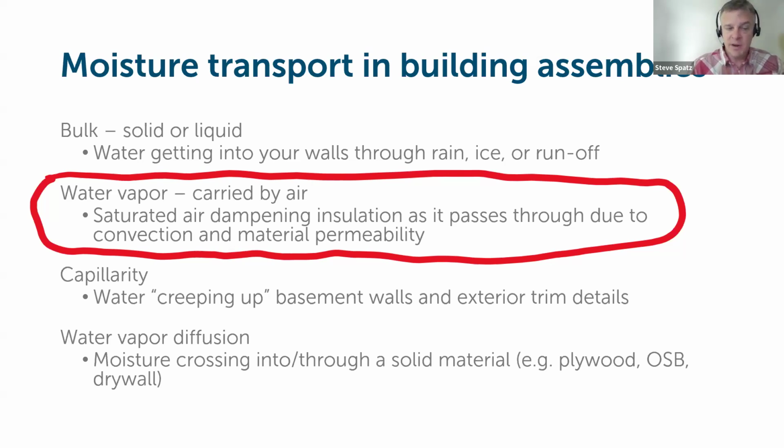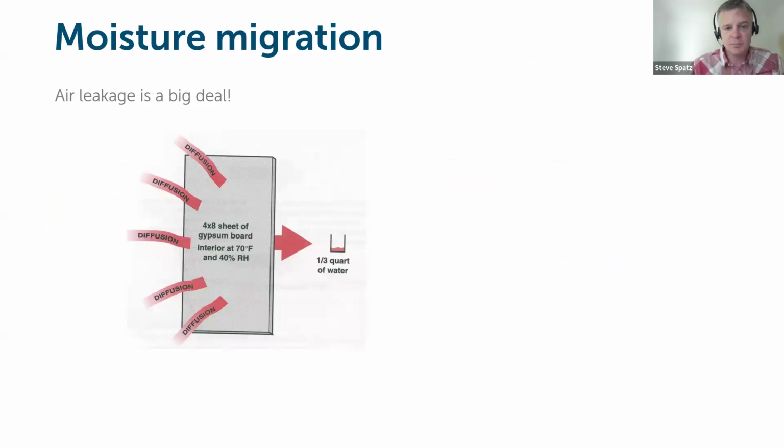So the air barrier, if that is in good shape and very effective, then you're not going to have a lot of pressure differential between inside and outside. So you're getting a bulk of your protection through that. But otherwise, you do need to be paying attention to the details of that vapor control.